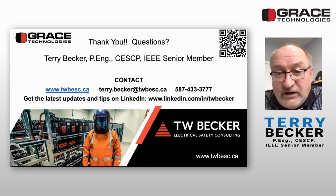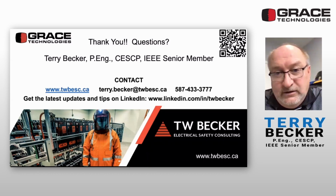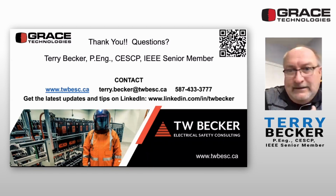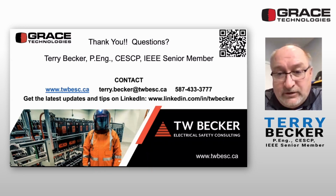If there's no arc flash hazard, you need PPE under 600 volts with finger safe hardware? Well, yes. Because the door's open and you're going in, there's no shock hazard, but your interaction with your meter, with wiring that your hand may move and the wire comes out, could still pose an abnormal arcing fault likelihood of yes. So keep the two hazards different: adding a whole bunch of insulation and getting rid of shock, versus interaction-based tasks that can create an abnormal arcing fault.